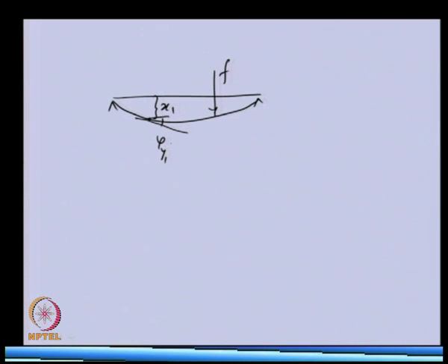Similarly, if we apply only a moment, that will not only give the angular displacement, but also the linear displacement. This is the transverse displacement, which is different as compared to the torsional one. In this particular plane, we are talking about the slope of the elastic line of the shaft. So, basically when we apply a force, both displacements and angular displacements take place.